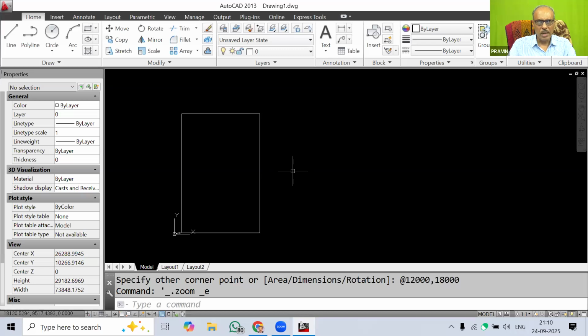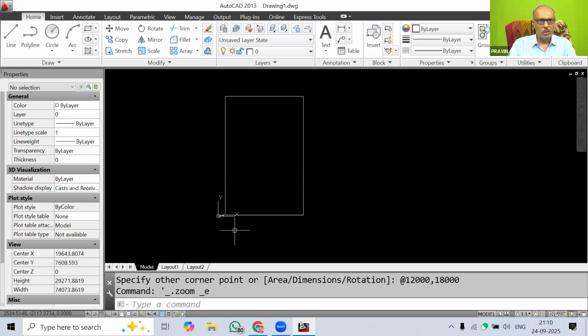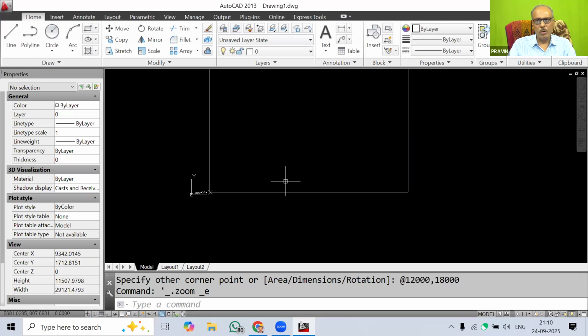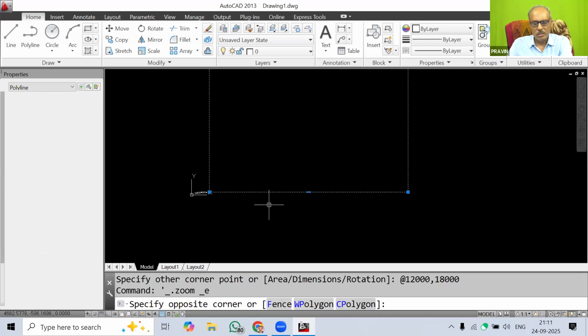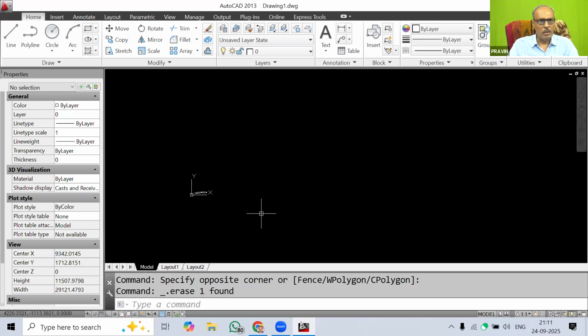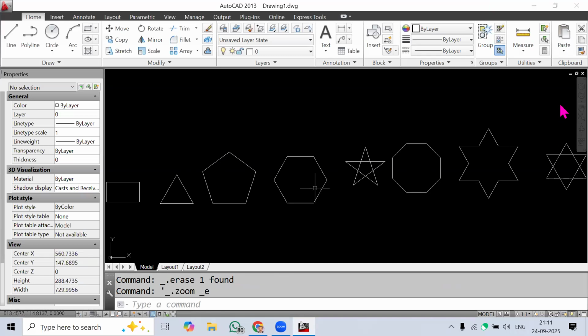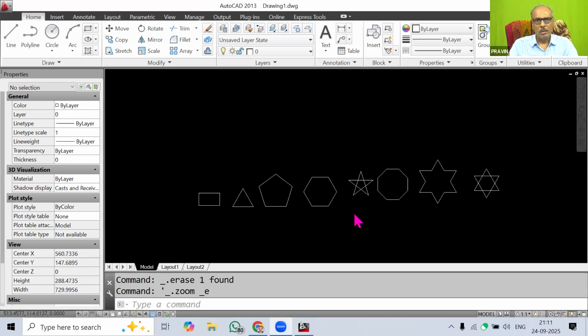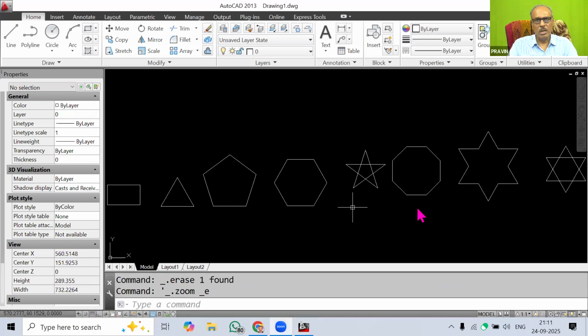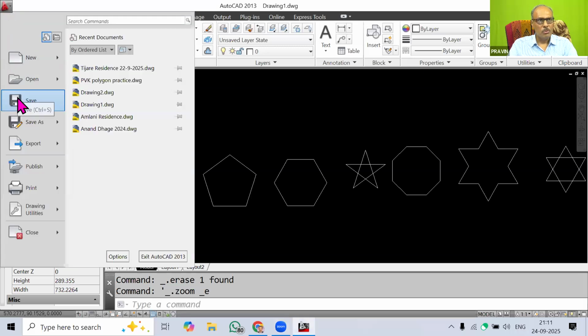Yes. Now if I want to save this, this figure file also we have to save. So I will just delete this plot. Now I will again double click, so you can just see that this is again the zoom extend command. So whatever drawing I have drawn came onto my screen, and now I will go here and type save.